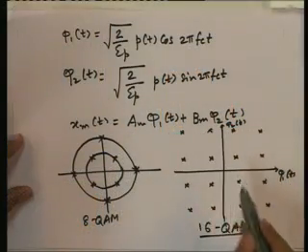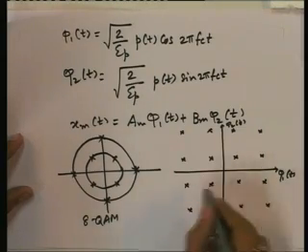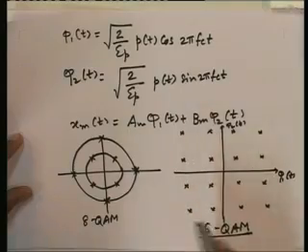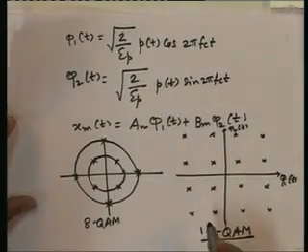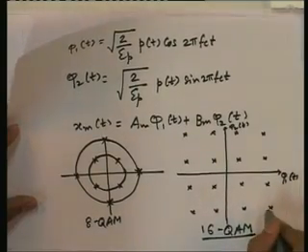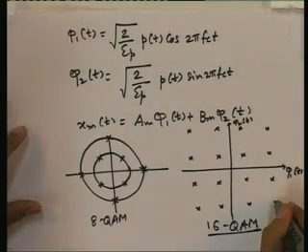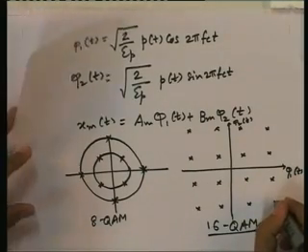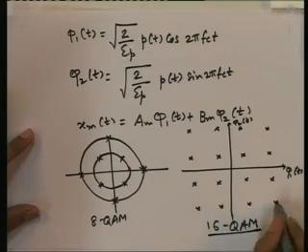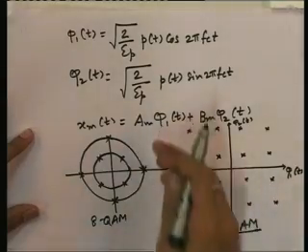So this is the 16 QAM constellation, and there are some other very standard constellations used. So using this constellation, if you want to transmit, what do we do? We take this phi 1(t), phi 2(t), and suppose this is m equal to 0, 1, m equal to 2, m equal to 3, 4, 5, 6, 7, 8, and so on till 15, because there are 16 points. If you want to transmit say m equal to 3, you can transmit 4 bits using this, because this is 16 QAM, and suppose you want to transmit the third signal, that is this point. How do we do it? You simply take the coordinates of this point, that is a_m, b_m, and then multiply a_m to phi 1(t), multiply b_m to phi 2(t), and then add them and transmit.